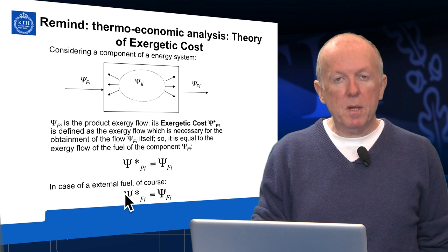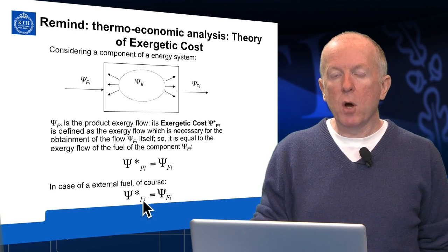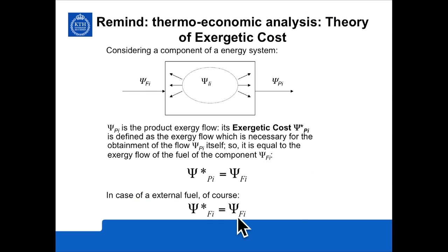So at the end, the exergetic cost Psi star F of the flow Psi F is equivalent to the exergy flow Psi F itself. So in the case of a component which is alone, the exergetic cost of the fuel is equal to its exergy content.